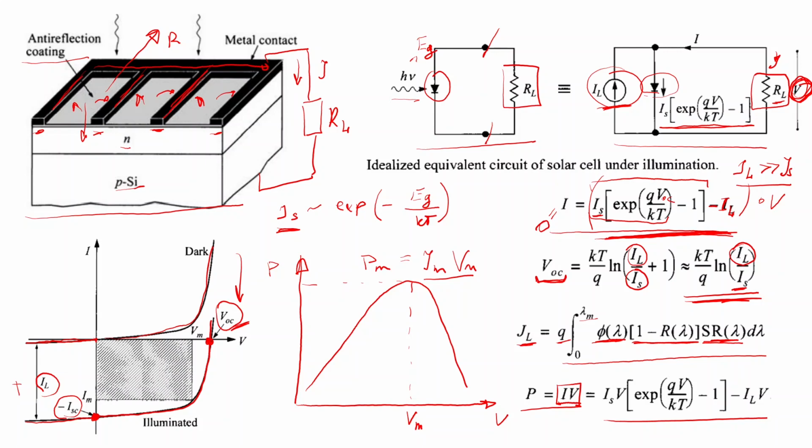So no, just think in terms of electrical characteristics. Electrical power, what we get out, is current times voltage. Current we know at short circuit condition. It's I short circuit. What is voltage? That's by definition 0. So if you multiply short circuit current by 0, you get nothing. The same stands for open circuit condition. You know voltage, which is VOC, but current is 0. So that's why you go from 0 to 0.